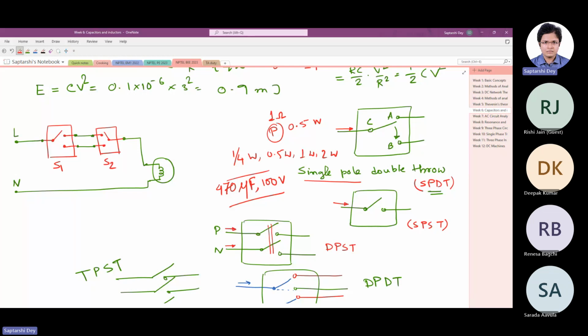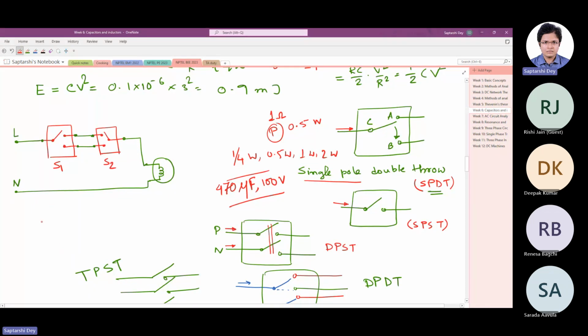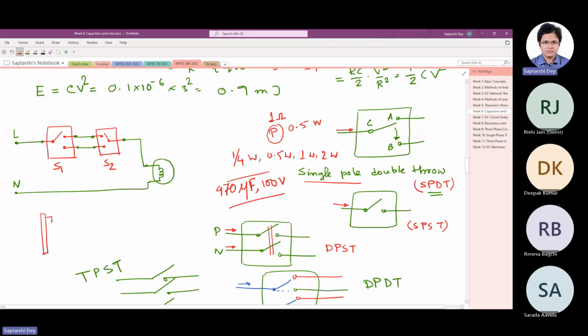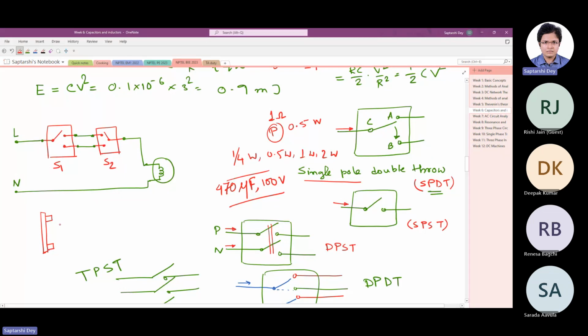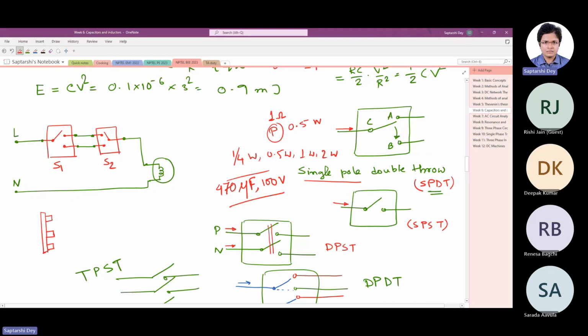These switches look similar to any other switch on the switchboard, but if you open the switchboard and look at the back of the switch, you will see that while other switches have two pillars, two points where you can connect a wire, the staircase switch will have three pillars, three ways where you can connect. So this one is the middle one here, and these two are the others.